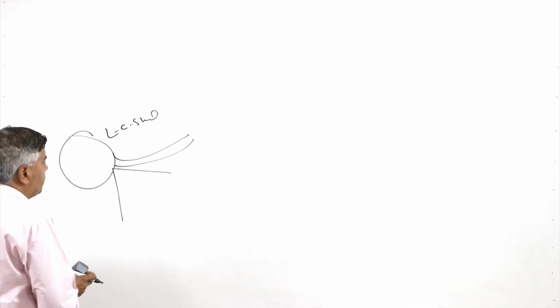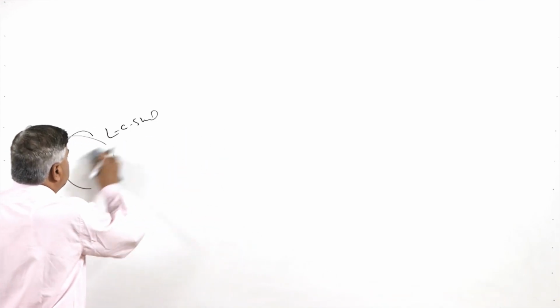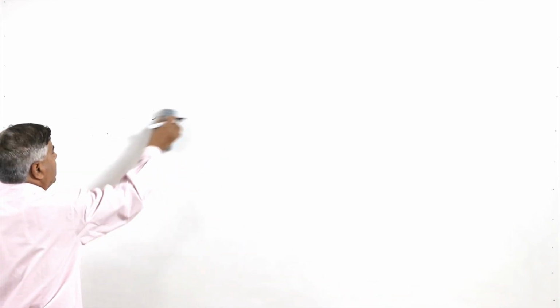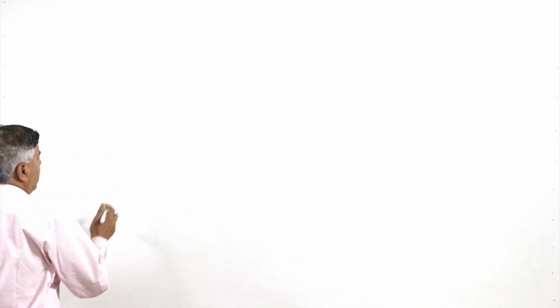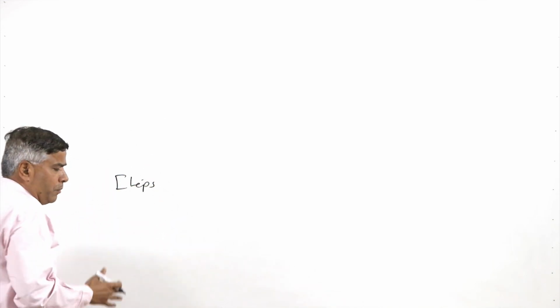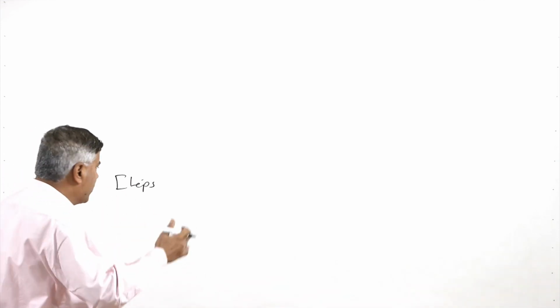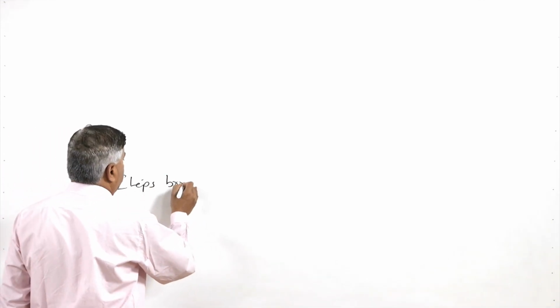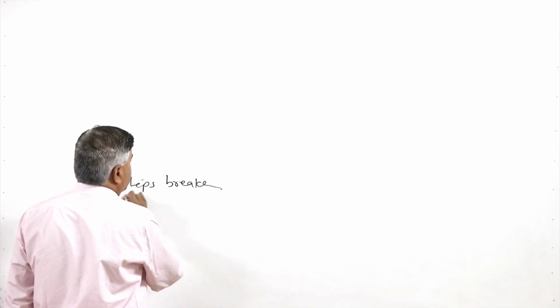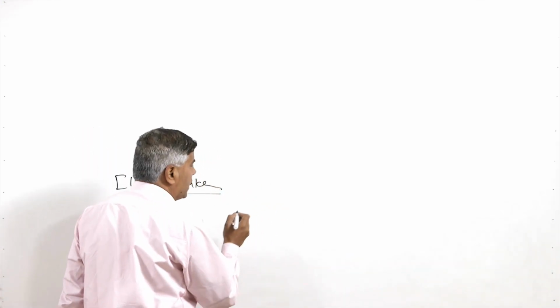So, it is important that unnecessary formation of long chips is avoided, and for that purpose chip breakers are used, so that once the chip is formed, it is tightly curled and broken away with the help of the chip breakers. The chip breakers are basically of two types.